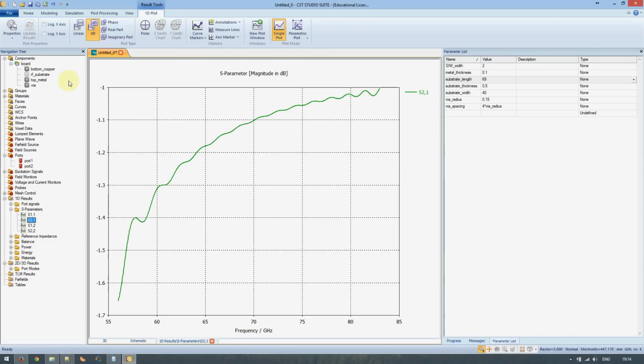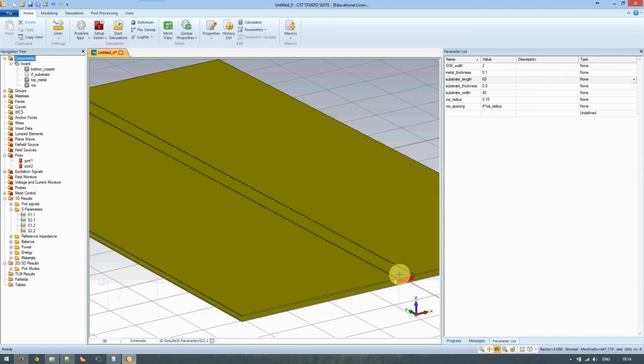In SIW, this varies according to various things. For example, the thickness of the copper, the height of the board, the dielectric constants, and the loss tangents of the board, according to relations that have been derived in the literature. I would suggest that you go and look these up if you're planning on doing a comprehensive study. I think that is all that is needed for now.